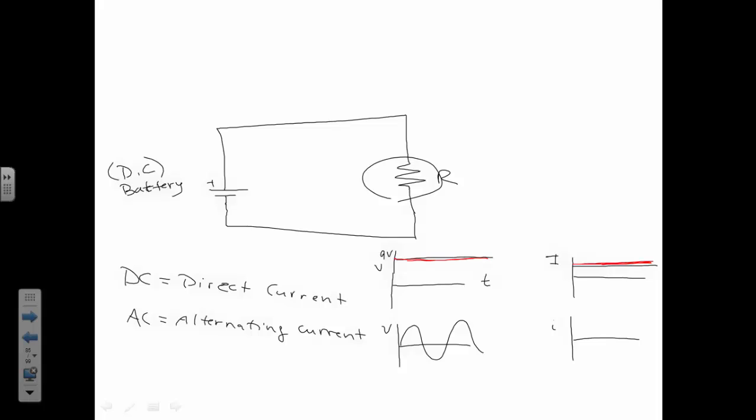Alternating current or voltage essentially means your voltage is oscillating from positive to negative, positive, negative. If you were to measure this coming out of here, it's 60 hertz, 120 volts. 60 hertz means every 1/60th of a second, I do one cycle. Remember, hertz is frequency: 60 cycles per second. So our voltage in these lights and everything else cycles 60 times per second. It goes through a full high to low, back to zero again.